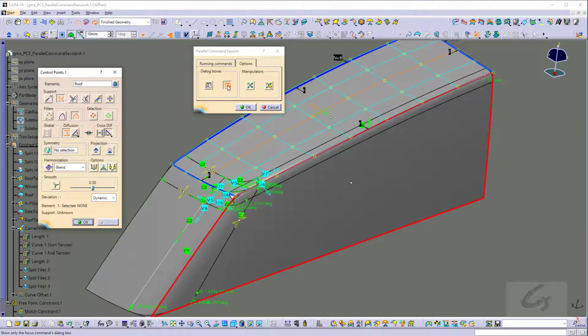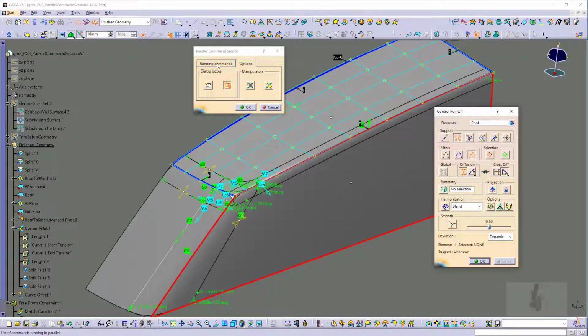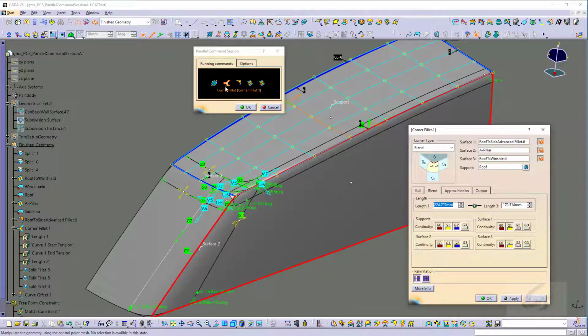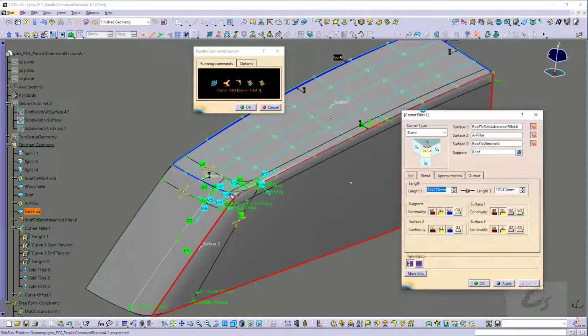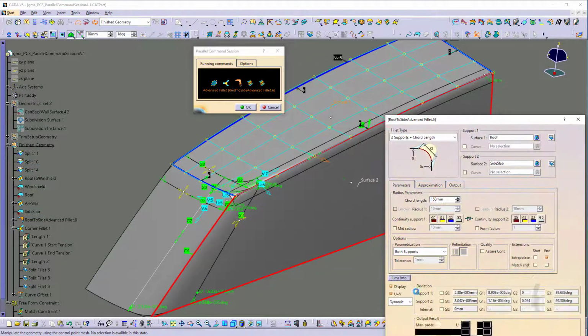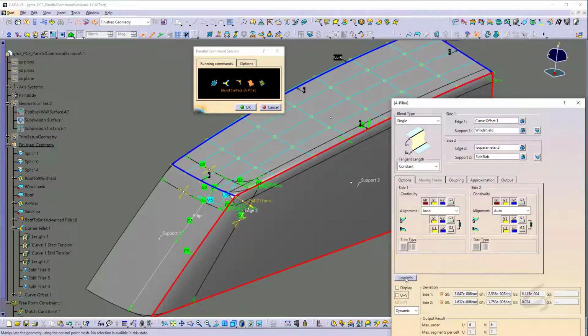And as you can see, the control point dialog box is shown on my screen as the feature itself is highlighted in orange inside of my running command list. So as I switch my selection through this interface, you can see that the dialog boxes are synchronized. This is my recommended workflow, with an exception that I will show in the next example. I have 5 features in this PCS, all showing detailed information, making the screen look a little bit cluttered. So in this case, I'm just going to go through each dialog box to unselect the detailed information.